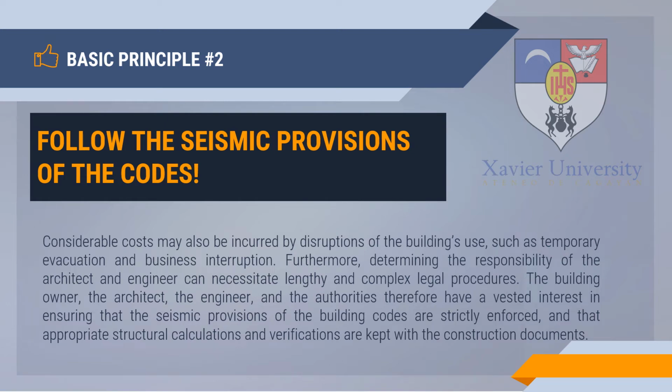So considerable costs may also be incurred by disruptions of the building's use, such as temporary evacuation and business interruption. Furthermore, determining the responsibility of the architect and the engineer can necessitate lengthy and complex legal procedures. So the building owner, the architect, the engineer, and the authorities therefore have a vested interest in ensuring that the seismic provisions of the building codes are strictly enforced and that appropriate structural calculations and verifications are kept with the construction documents.